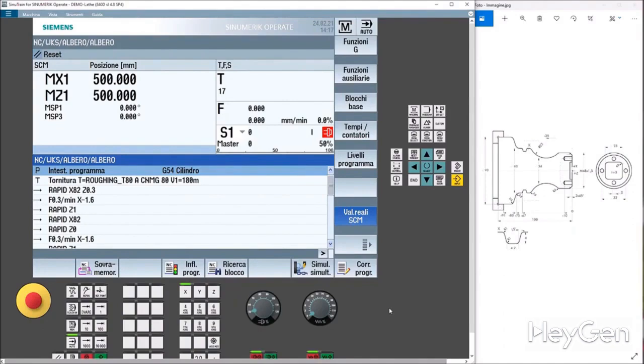When defining a casting, always stick to the maximum tolerance. Keep in mind that you will probably be clamping onto a raw piece, so the part might not be perfectly concentric. So, either you keep yourself in a safe position when you get close, or you always define it a bit chunkier than it actually is.